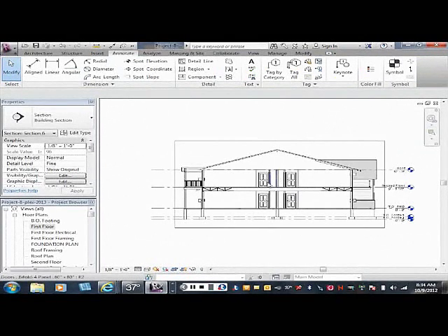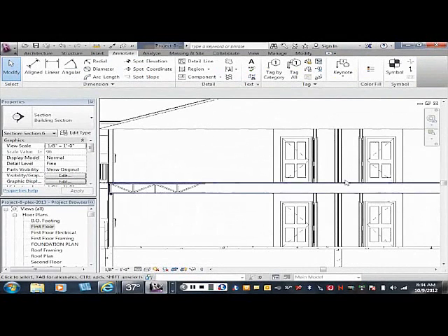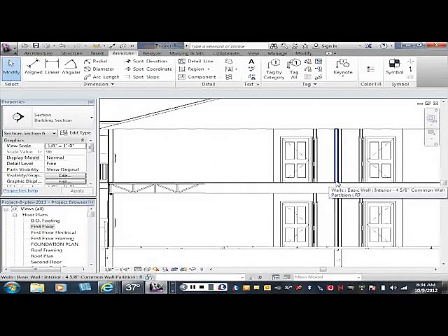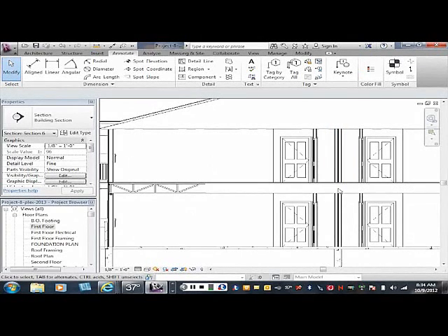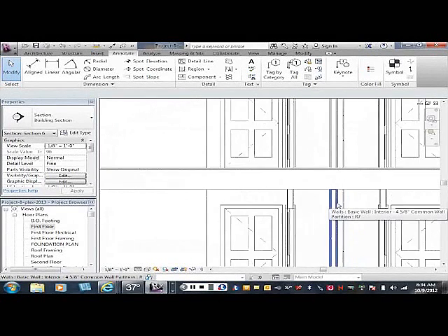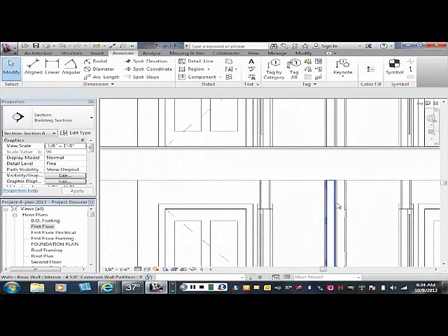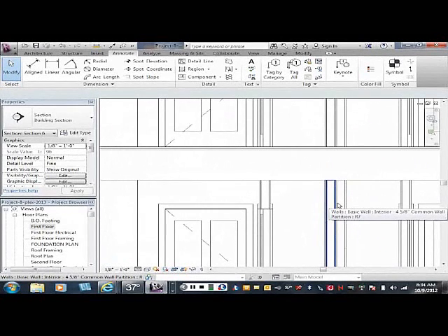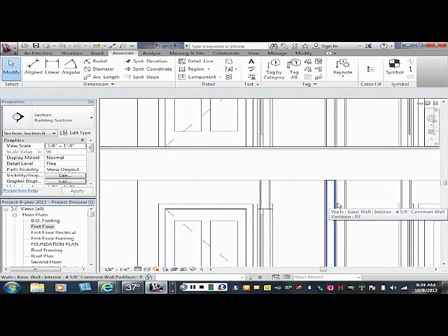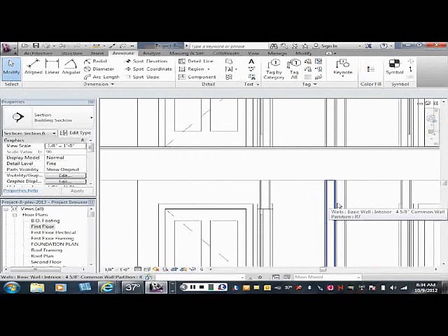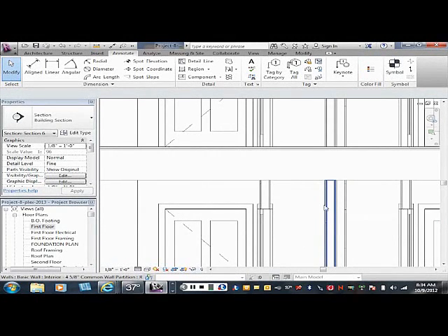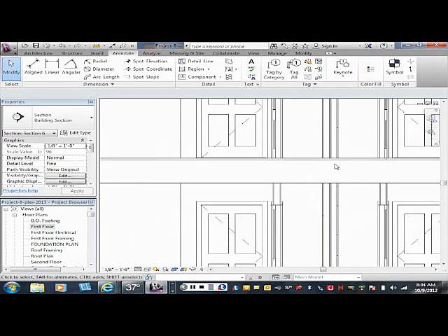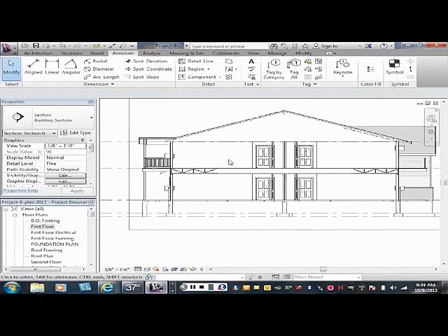Could be. Okay, so we might want to do some detailing in the middle here where these trusses come together, because we don't have a 52-foot truss. We probably have two trusses that set on the center bearing wall, and I can let you figure that out on your own. We do have this party wall which has separation between it. We want to keep sound down, so maybe we want to keep that inch air gap going all the way up through the building so we don't touch anything even in the floor joist space. So we might work on that a little bit in there.